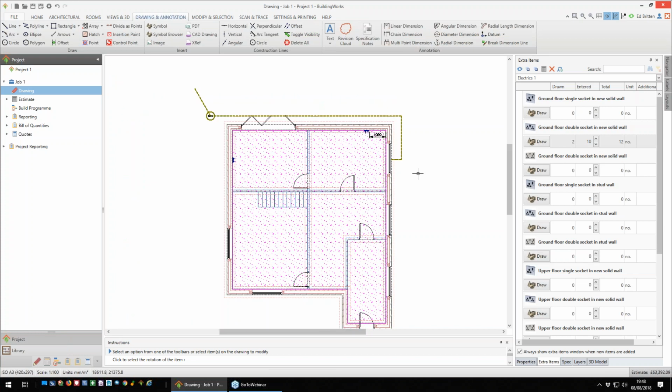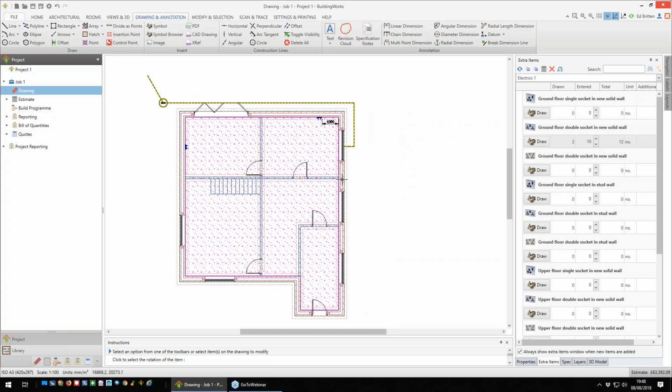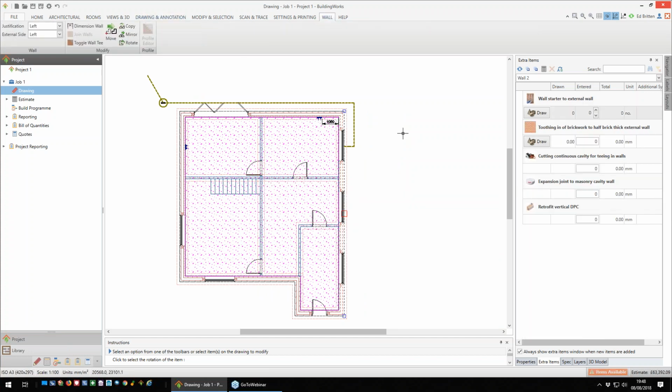What that means is later on, once you've got a completed drawing, you can switch different layers on or off and actually produce different versions of the same drawing for different trades. So you could have one that shows all the electrics for your electricians, one that shows all your pipe and radiator and boiler layout for, say, your plumbers, for example. You can have one that's got none of those details, and it's all the details such as all your wall dimensions for, of course, the guys who are doing your groundworks and all the masonry shell.